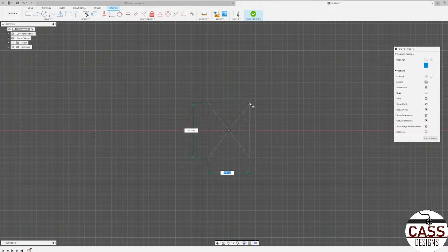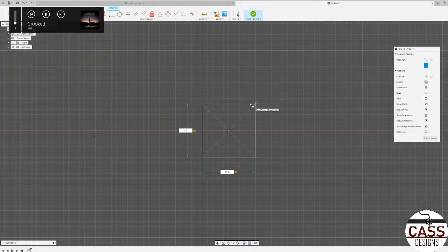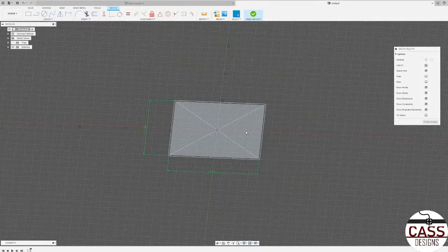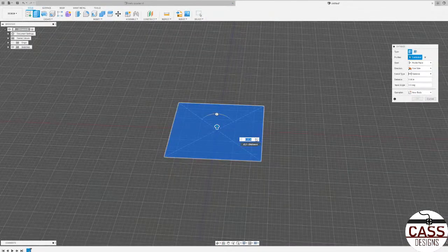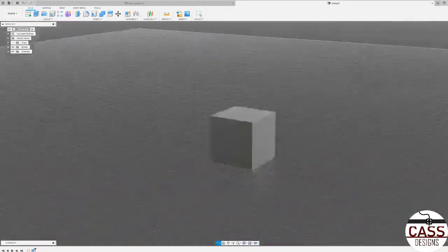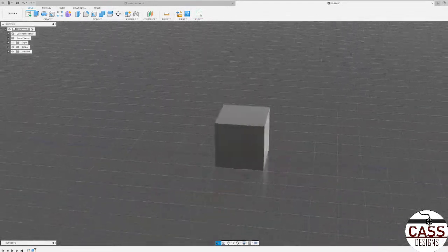And let's say a keycap's, I don't know, a 1/2 inch by 1/2 inch. So we do a 1/2 inch. Oop, didn't mean to raise volume. Click enter. And then now we have that shape that we're going to want to extrude. And let's say it's another 1/2 inch. Let's say it's a perfect cube. So this is what we're starting our keycap with. And we're just going to cut away until we have what we want.